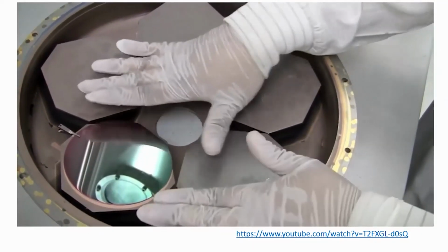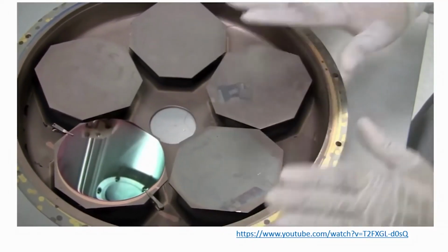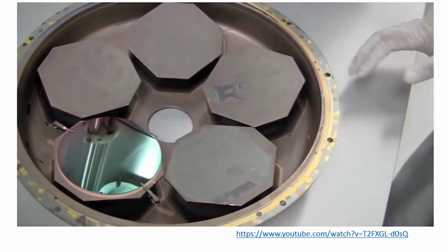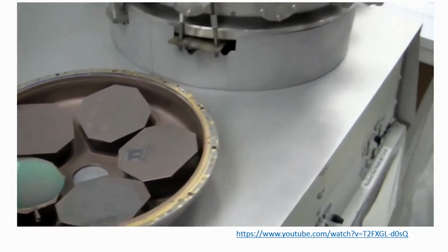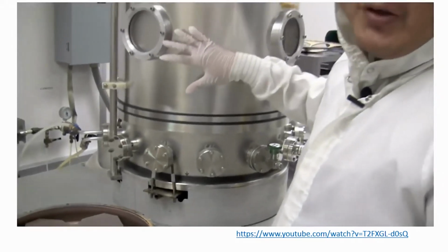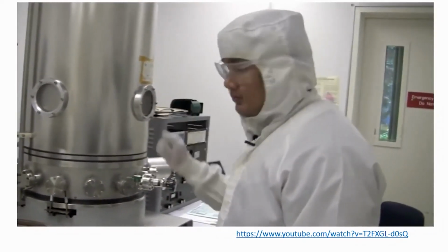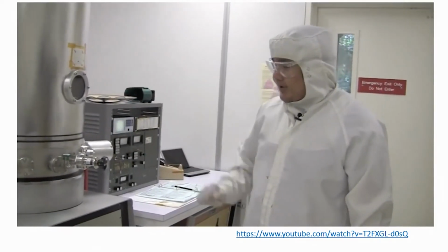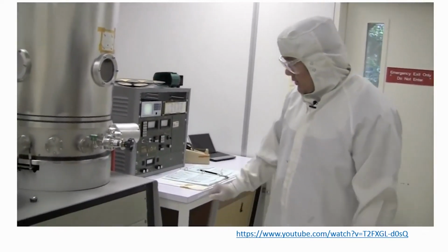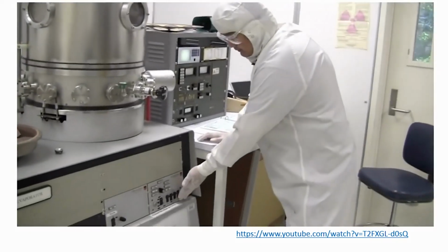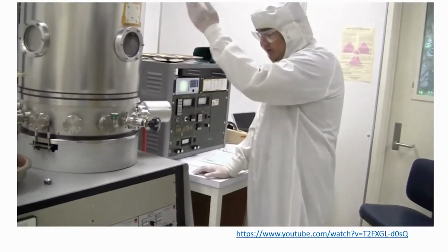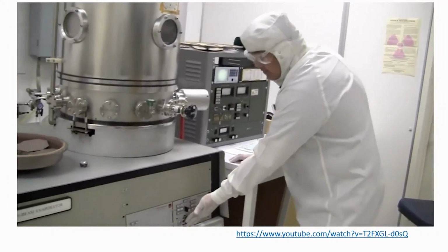Once you've mounted your wafer and you want to put it in the system, you would need to vent the system, because right now it's in high vacuum. So what we're going to do is now we're going to vent the system. Now that we've been venting the system and the pressure has reached 7.4 times 10 to the plus 2 at ATM, we can actually open the chamber. To do that, we would turn the vent off and raise the chamber with the toggle valves.